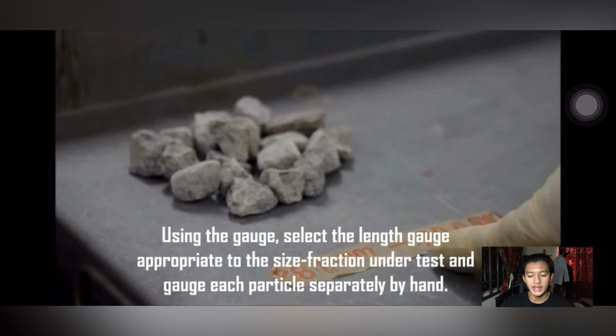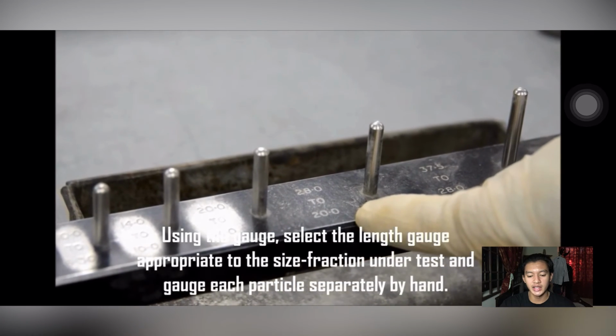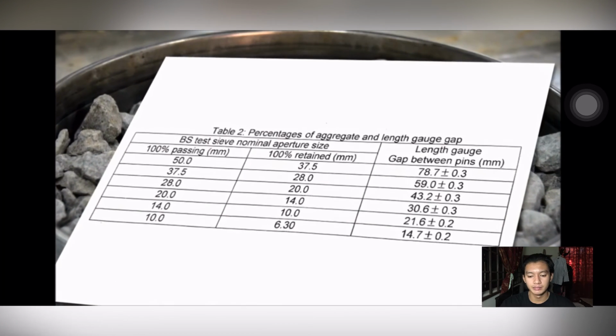Using the gauge, select the length gauge appropriate to the size fraction under test and gauge each particle separate by hand. Refer to Table 2 of Highway Laboratory Test Manual.